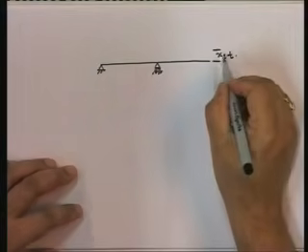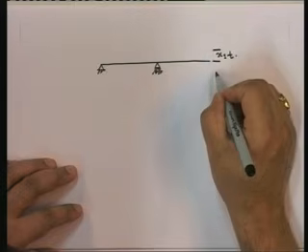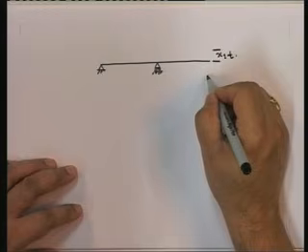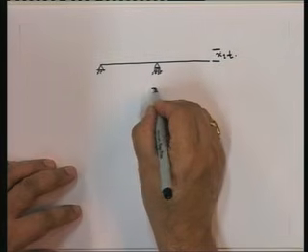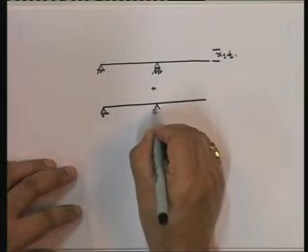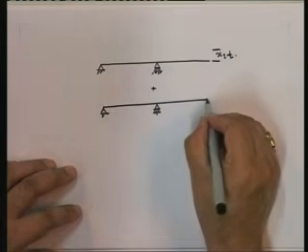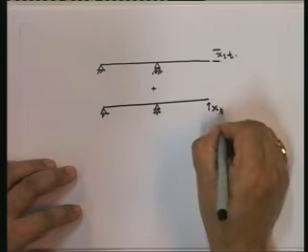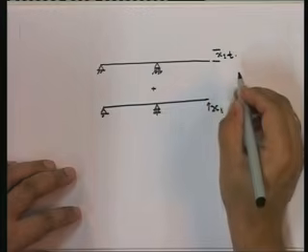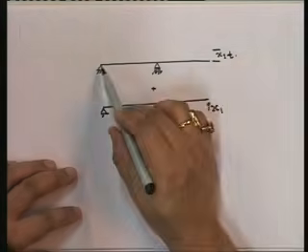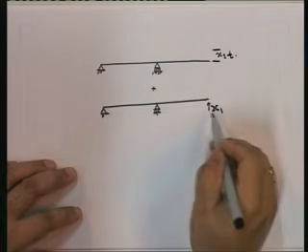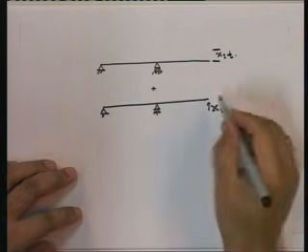Note that if this does not go up or down due to the differential temperature, you will not have any support reaction here, you will not have any x1, and then if you do not have any x1, the temperature will not have any effect on the structure. So therefore, we have to first see the situation that due to the temperature, is there a displacement here? That's my first, and then of course we add up this and put it equal to 0.